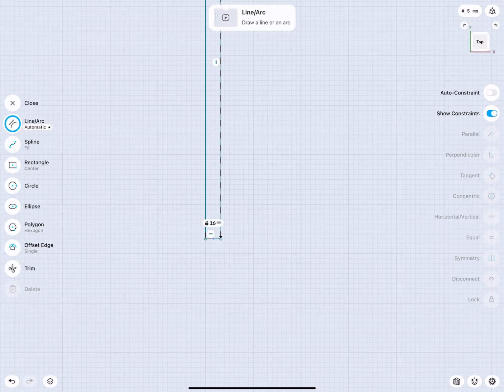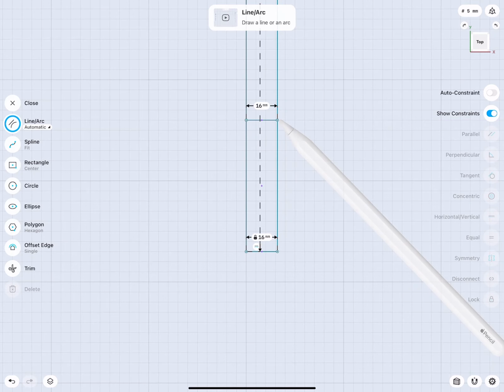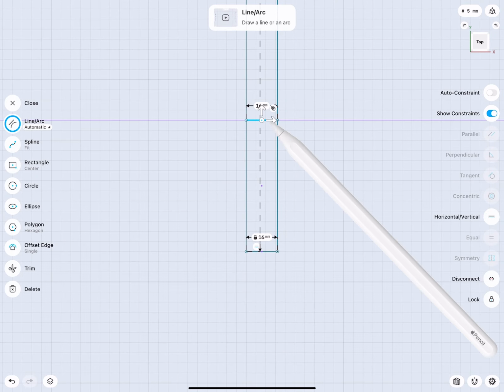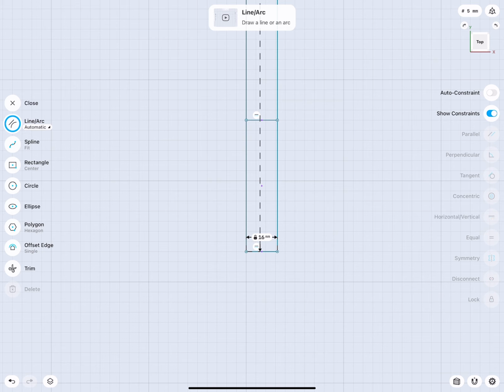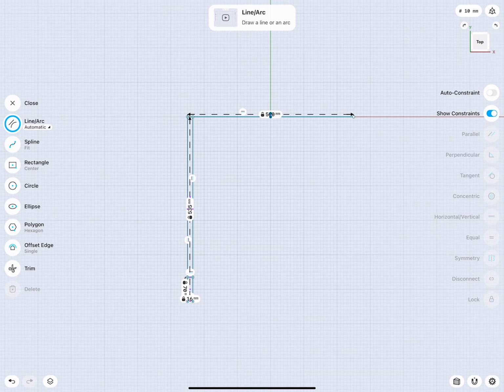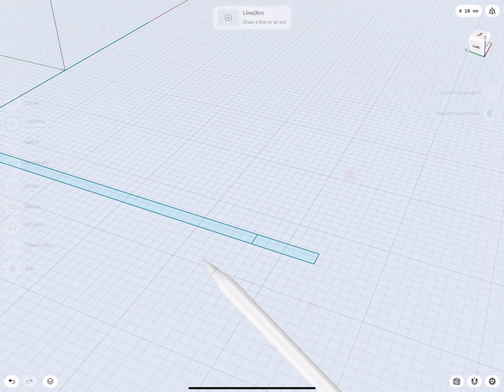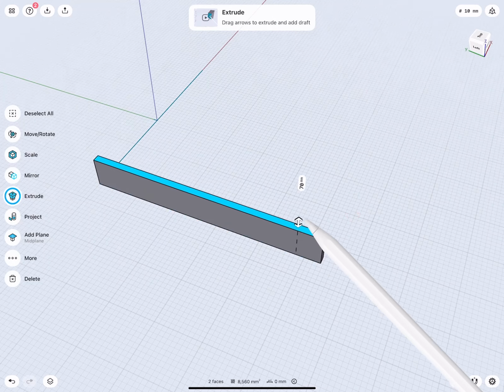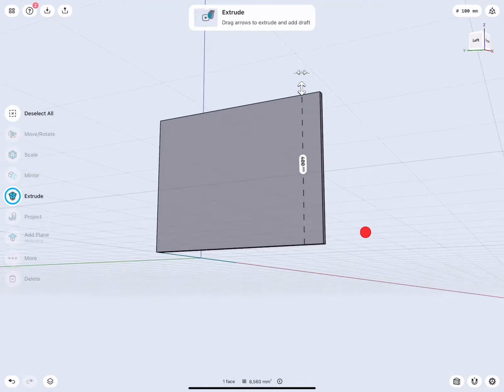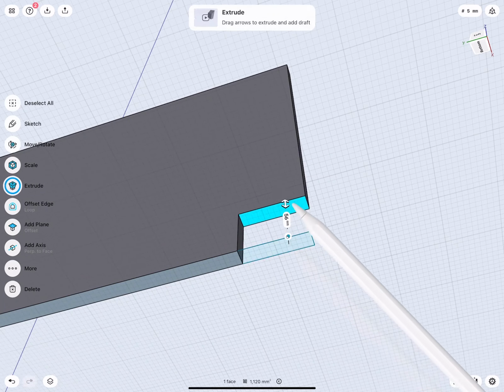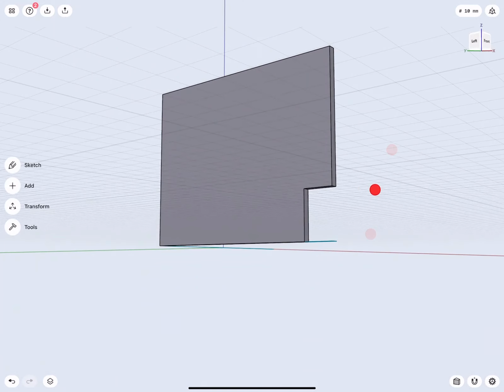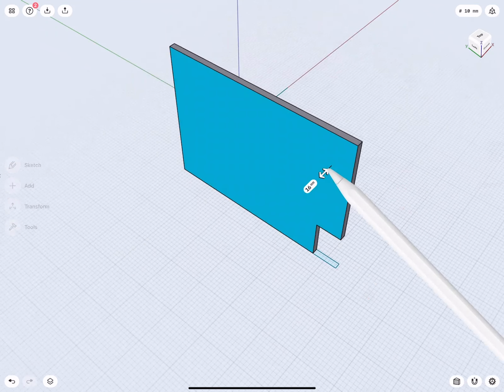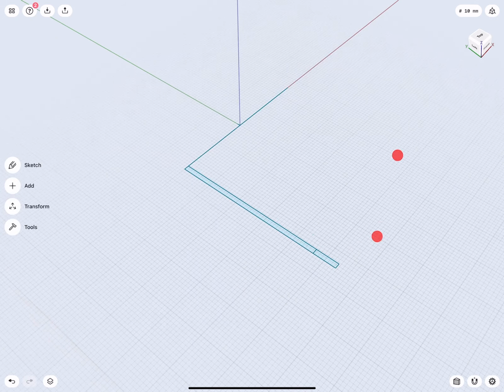Very good. Okay. Now I can draw here another line. This is actually for the toe kick. Horizontal. And then these two should be 70 millimeters apart. Very good. Okay. So that's nice. A little preview: later we can extrude the sideboard up, and then to cut the toe kick, we extrude another time in and cut it out. Very good. So let's remove everything.